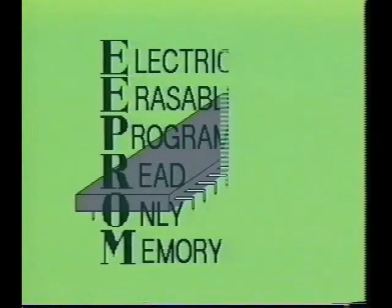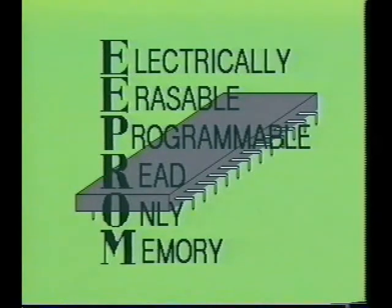The EEPROM, or as just mentioned, electrically erasable programmable read-only memory device, is a popular alternative to the EPROM just discussed. As you recall, the major disadvantage to the EPROM was its inability to be reprogrammed quickly. This was due to the fact that the EPROM had to be subjected to a concentrated ultraviolet light source for a period of 15 to 30 minutes before the data was erased. In regard to reprogramming the EPROM, it was an all or nothing process. You either erased all of the data or none at all.